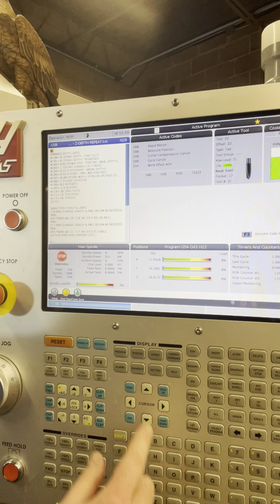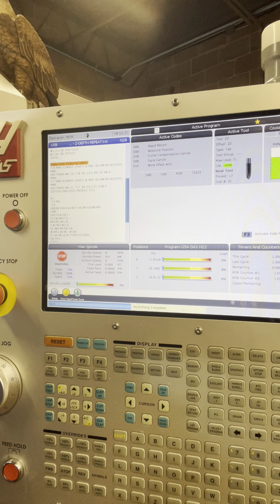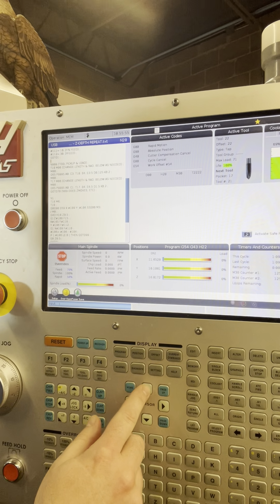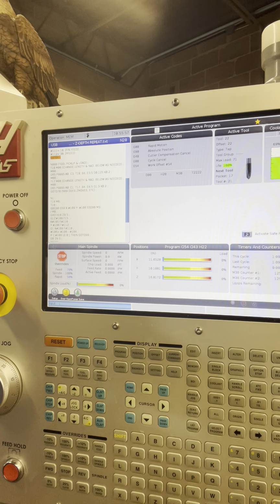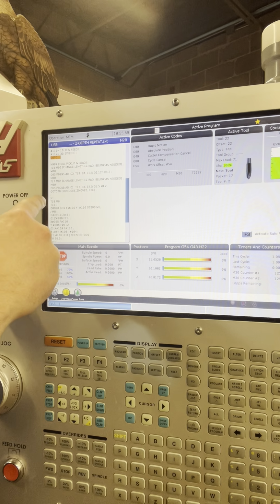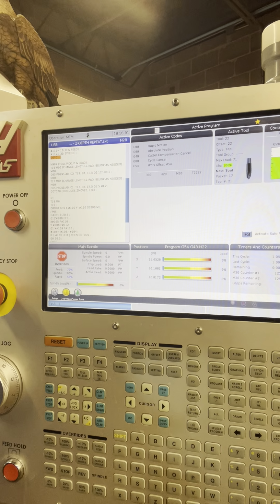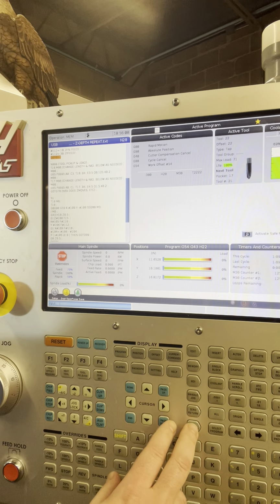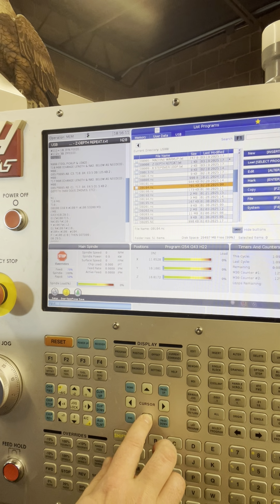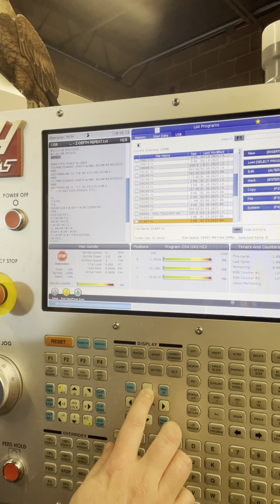The other thing I do is N999, so we're consistent, and that's always at the top there. But you can see my go-to here. So when we're running this program, it hits the go-to one and jumps down over top of the tool touch-off. Does it kind of make sense? Yeah. Okay. You guys have any questions? Yeah. All right. Good. Let me just go back to that other one. I should have given them better numbers, sorry.